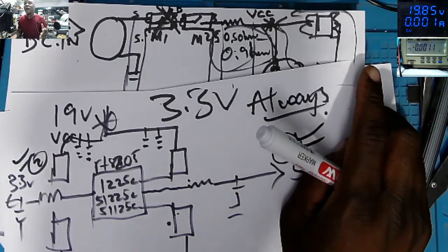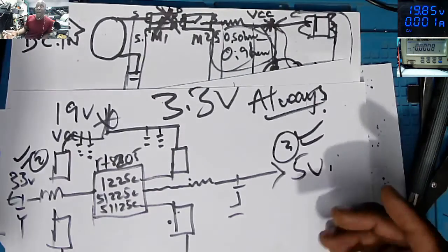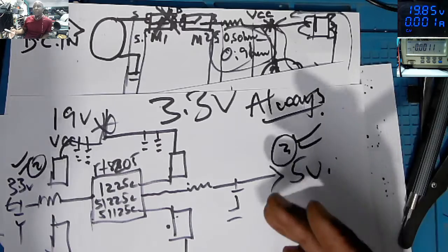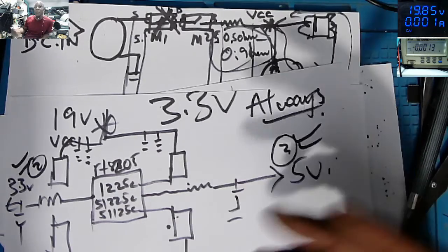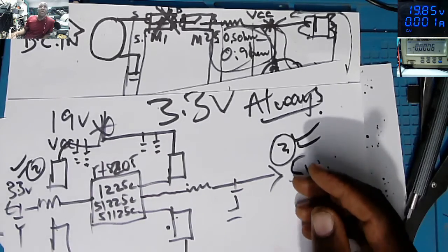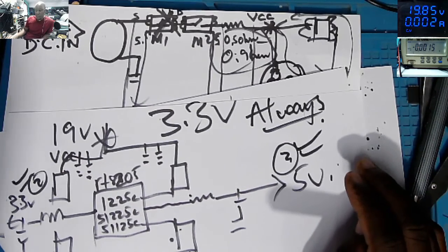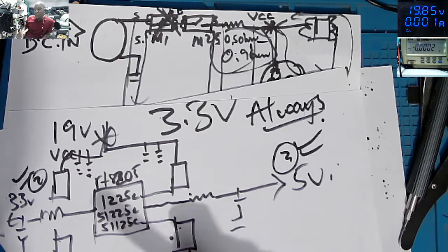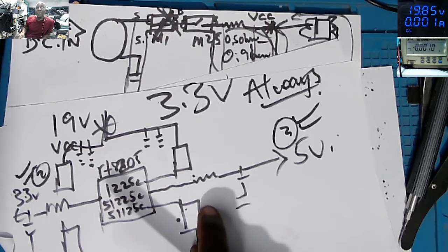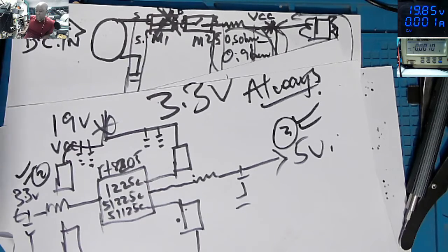Of course, we have other things like the RAM power supply, faulty GPU power supply, and the VCore power supply for the processor can be faulty. But if a power supply is going to die first, this one will die first because it's always on.